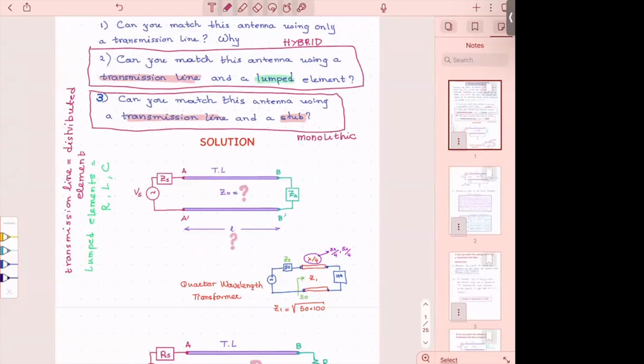Do you remember the word monolithic? From the monolith that was in the 2001 movie. It's a Greek word. It means made out of one thing, one type, one material. Now it's not one material, there are multiple materials, but one type. So this is monolithic design, monolithic circuits. When you hear integrated monolithic circuits, all right? It's this, all distributed. When you hear hybrid designs, they include both distributed and lumped. All right, so that's the terminology.